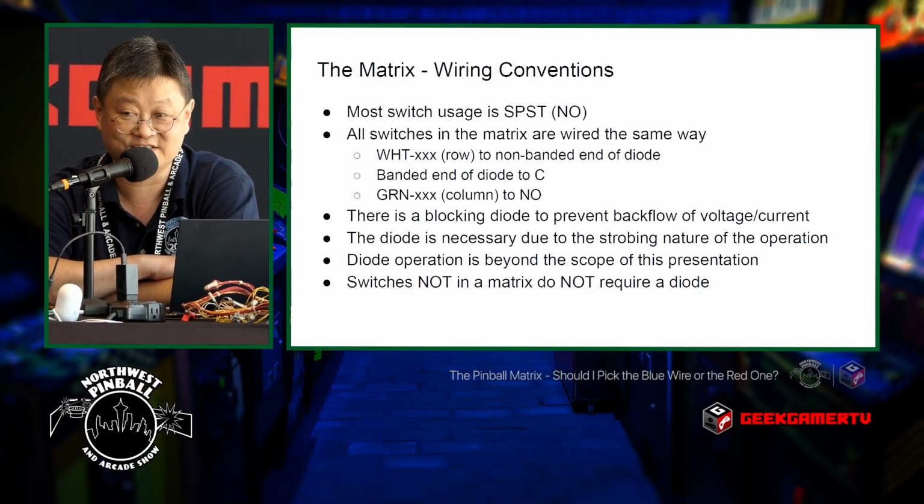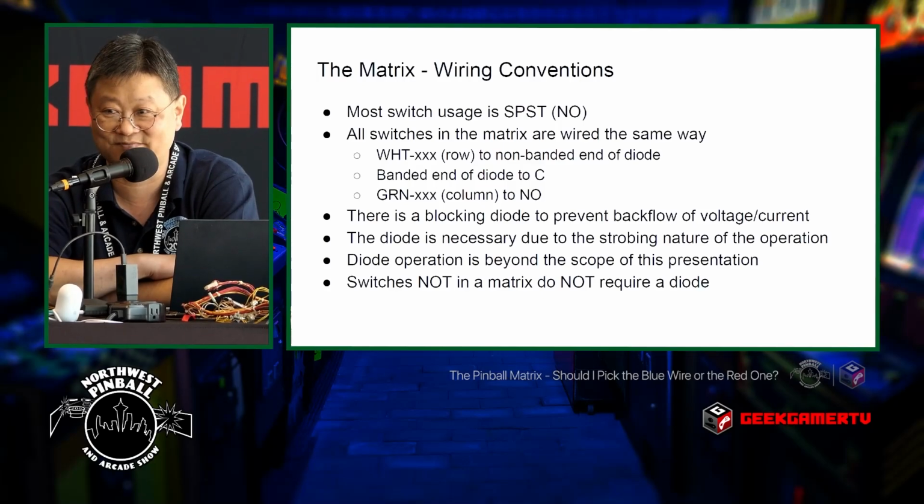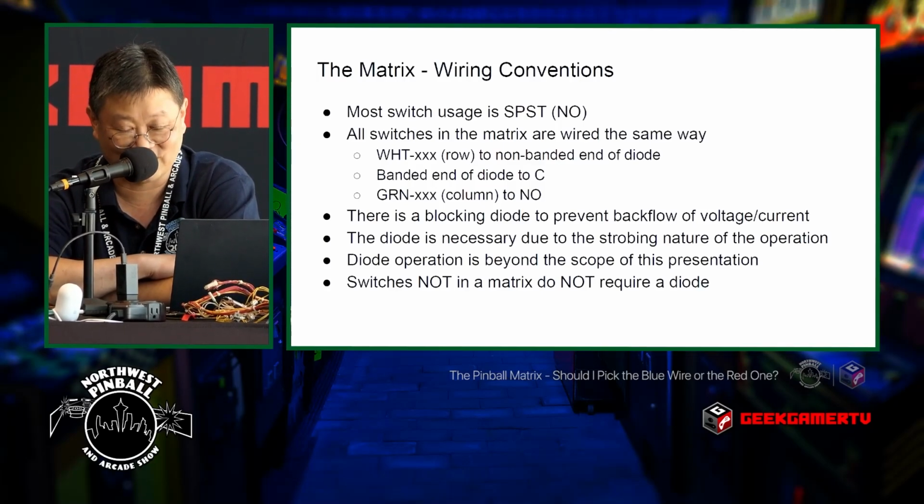They're all wired the same way. This is a problem that a lot of people don't realize. Oh, well, the diode direction doesn't matter, right? We could wire it to the C or the NO, it doesn't matter. All the terminals are the same, right? No, they're not. This is why I'm going to the trouble of helping you understand that they're not the same, and they are labeled this way for a reason.